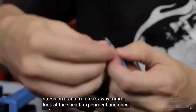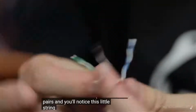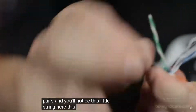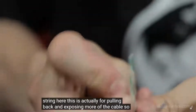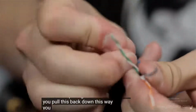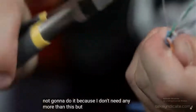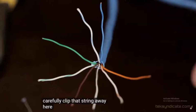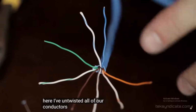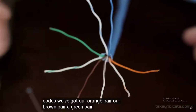Now once we're here, we want to separate out our pairs, and you'll notice this little string here. This is actually for pulling back and exposing more of the cable. So you pull this back down this way, and it'll just cut the cable down. I'm not going to do it because I don't need any more than this. But you can just very carefully clip that string away. Here I've untwisted all of our conductors into our different color codes. We've got our orange pair, our brown pair, a green pair, and the blue pair.